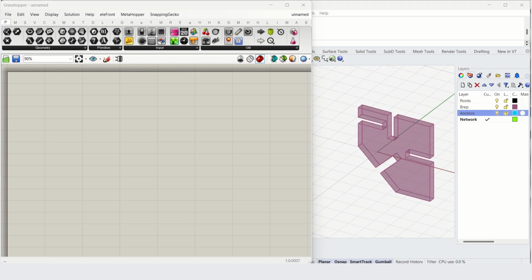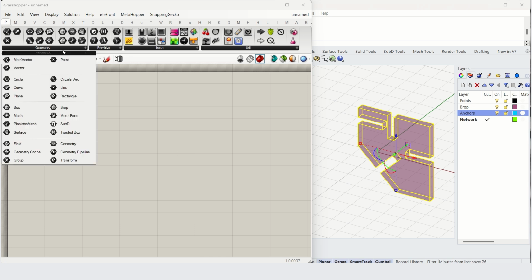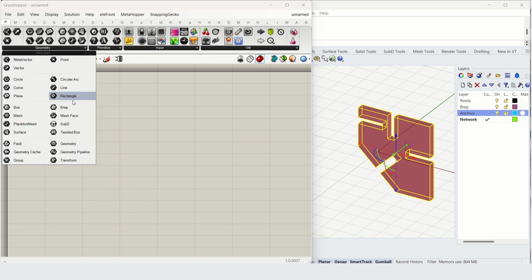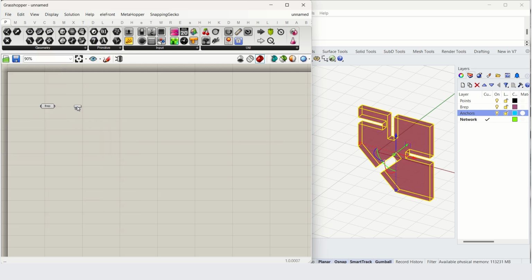For this exercise, begin with a basic flat piece with notches that could be laser cut out of MDF. Reference this to a B-rep param and pass that into a mesh param to convert it. Assembler works with meshes because they are computationally faster, and this will have an impact on performance in large assemblages. Note that these must be closed volumes, not open polysurfaces.